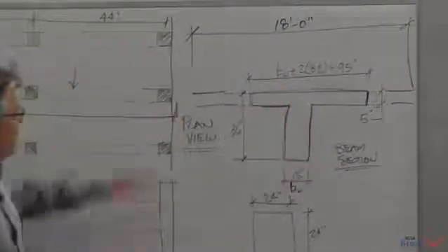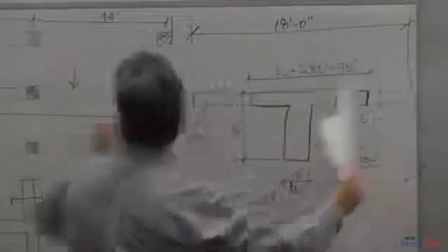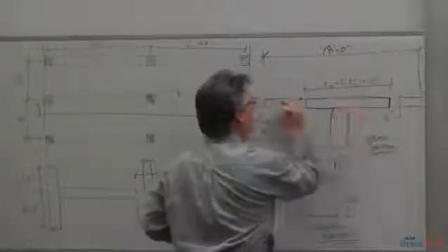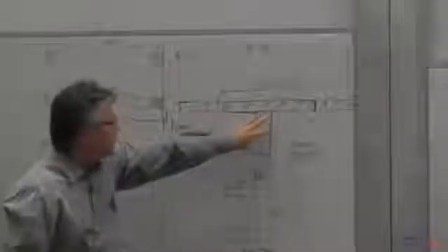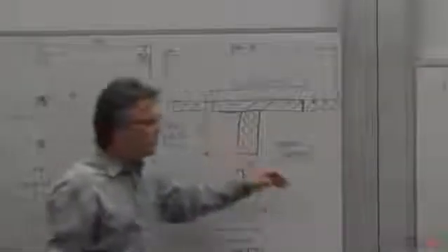the line load on this beam is going to be the weight of 18 feet, a section right here, 18 feet of width. So the way I've done it, the 5-inch slab part weighs 62.5 pounds a square foot. The rest of this, I calculated the weight at 150 pounds per cubic foot, and I divided it by 18 feet to convert this chunk of concrete into pounds per square foot. If I did that correctly, that should be 15 inches times 31 inches times 150 pounds per cubic foot divided by 18 feet. So the beams are equivalent to 26.9 pounds a square foot.